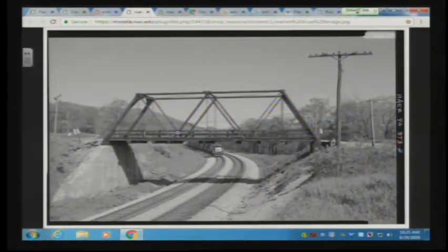And if you think about it, it makes sense because if loads are being transferred between all the structural members on this truss, if this one breaks, what's going to happen to the other structural members in the truss? They're going to have more load, right? So in other words, if somebody didn't bolt this in properly, if the fasteners were not dealt with correctly, or if there was a flaw in our structural material, maybe it was cast improperly, or there's a weak spot or a narrow spot.